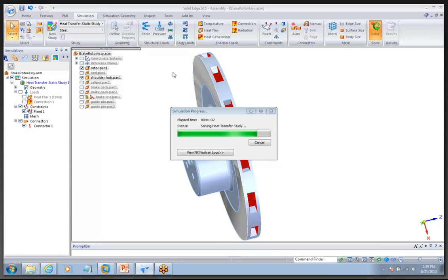So you can use the internet, or whatever sources you normally use to get material properties, and enter that conduction coefficient. Now with convection, let's say I've got this surface here that's heating up, and now I've got diffusion, so the molecules here are bumping into the air molecules, or whatever fluid this is. Let's say it's water, or, well, we'll just say it's air. So they're bumping into the air molecules, exciting them, and you've got that transfer of energy.